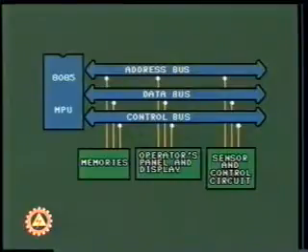Considering the technical specifications, reliability, repeatability, and economic factors, we now take up the circuit design of the system in accordance with the block diagram. We select various devices and components to convert these defined blocks into reality. We know that microprocessor 8085 can source 400 microamperes and sink 2 milliamperes of current. This current rating suffices only for one transistor logic load.